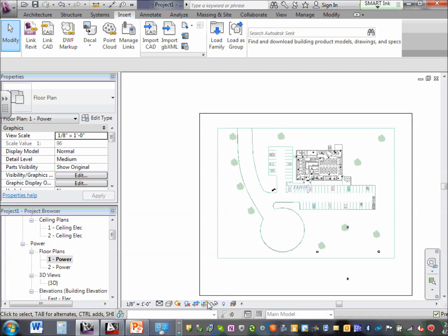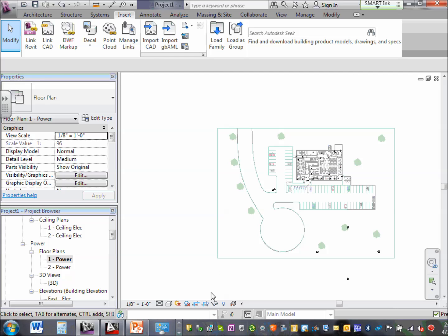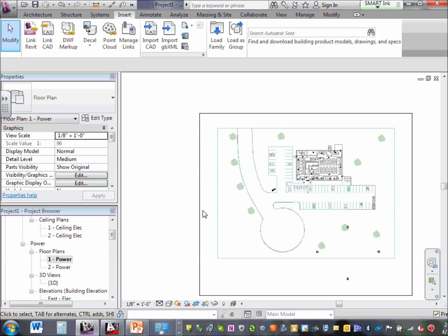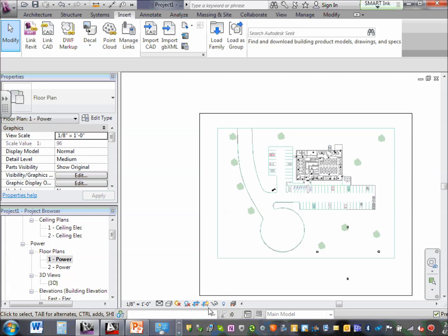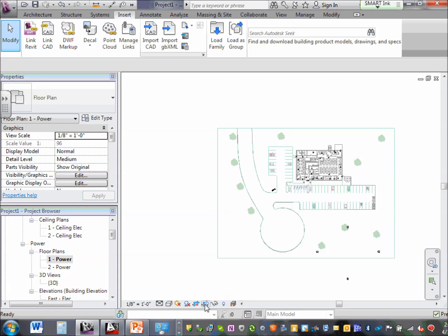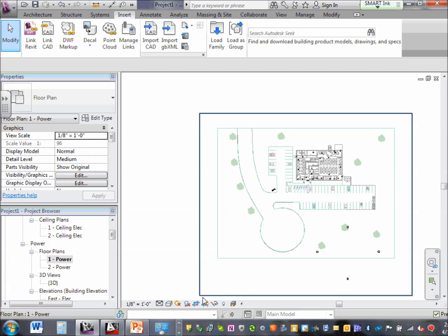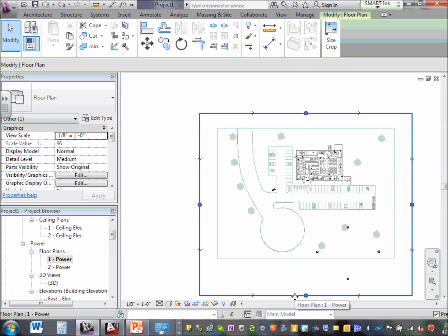That crop region. Now, click on it and it will appear. Double click on it and it will disappear, right? Now make sure that you have the crop region like this. So hide crop region, bring crop region. I need the crop region. Cool? So everybody got the crop region now, exactly like you crop a picture. You're cropping a 3D though. Remember, this is a 3D model.